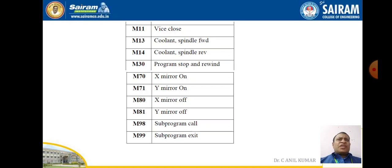M70 is for the X mirror on. M71 is with respect to the Y mirror on. M80 refers to the X mirror off, and M81 refers to the Y mirror off. M98 is the subprogram call. M99 is the subprogram exit. See, these are the miscellaneous codes normally used in different types of programs when we are manufacturing different types of components.